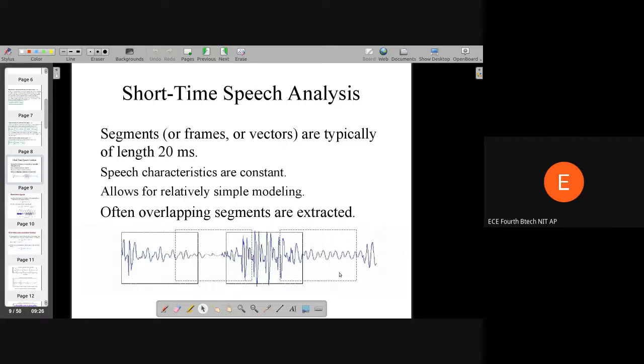Even with detailed classification based on acoustic phonetics, each of the sounds has different properties, different resonances, and so on. If you take a chunk of a speech signal and another chunk at another place, you will never get the same Fourier spectrum. What does this mean? The previous case, a perfect sinusoid, was a stationary signal. This is not a stationary signal.